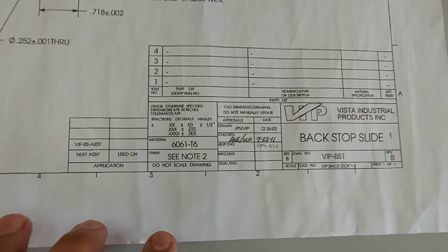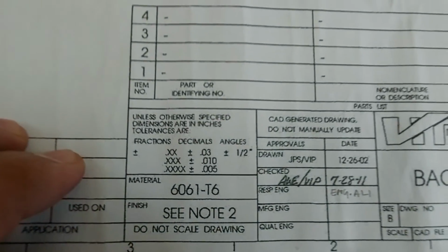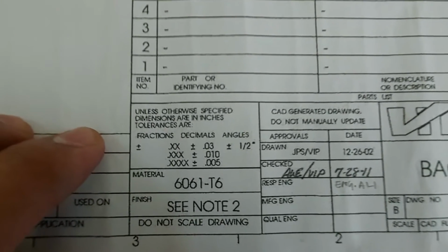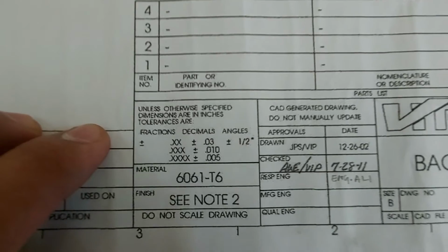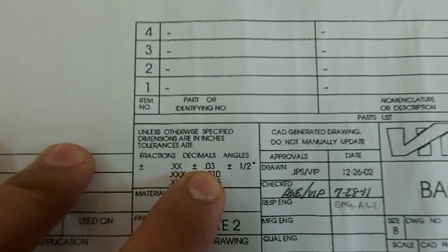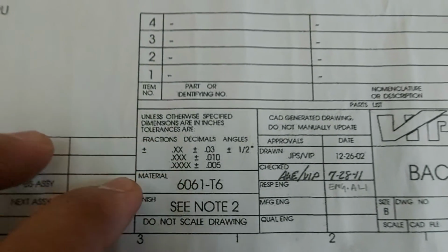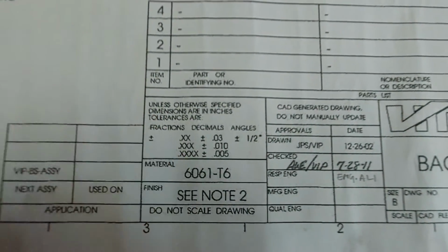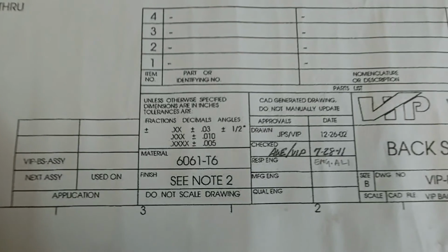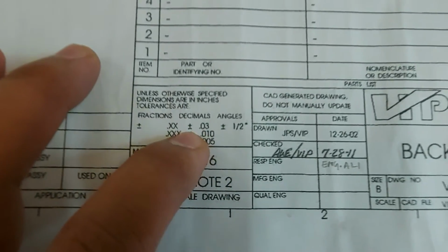Another important component inside the title block is tolerances. These are the tolerances mentioned. Basically there will be different types of tolerances. Here it is mentioned .xx. When it is written, the tolerance will be plus or minus 0.03. Sometimes they give the code, so you have to follow the standard code. You will go back to whatever code, ANSI or ASME, refer to the code book and try to find the tolerances. Here they mention the tolerances itself.